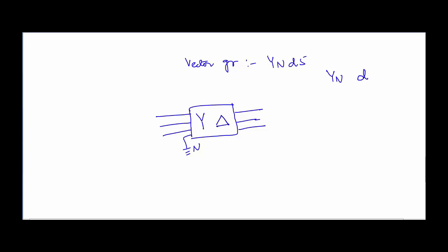So this is connected in delta, and the 5 says that this delta side lags the star side by an angle equal to 5 into minus 30, which is minus 150 degrees. So if we have either voltage or current at this point, which is A at an angle of 0 degrees, here it is going to be A at an angle of minus 150 degrees. So this is what this expression exactly means.